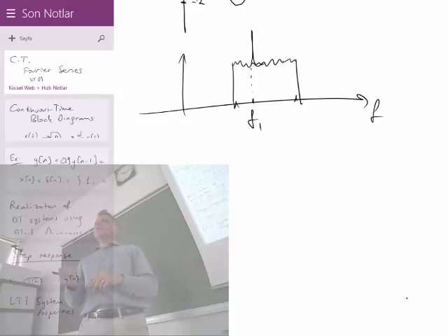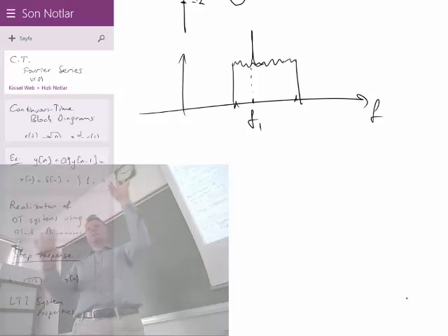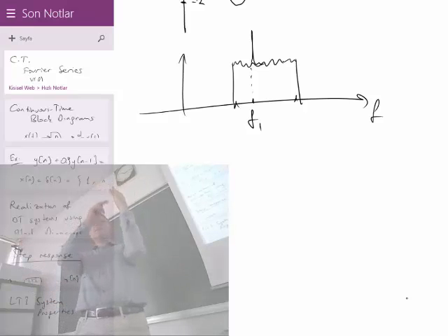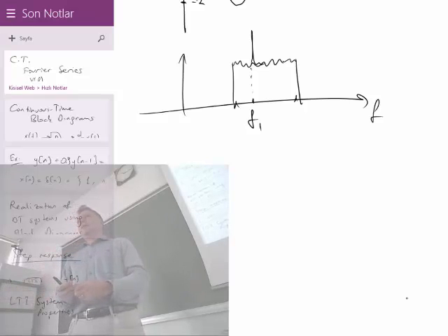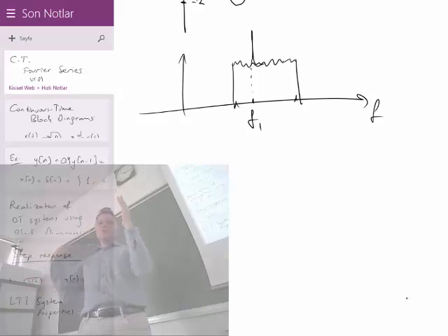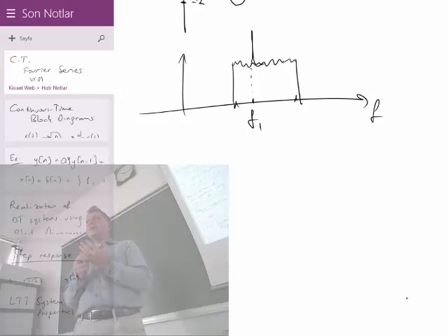What MP3 does is it converts the signal into frequency domain first and looks at the harmonics, contents. These strong harmonics are quantized using some bits, but the lower magnitude harmonics are quantized using less number of bits. Therefore, most of the bits are used for the reasonable component only, and for the useless components that we cannot hear or anything, they use less number of quantization bits, and the overall number of bits is reduced.